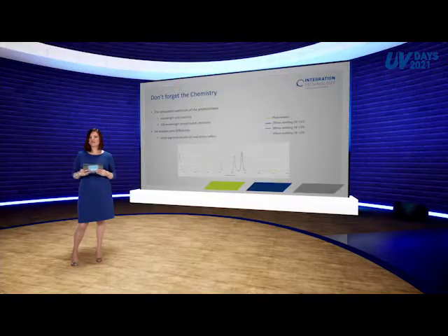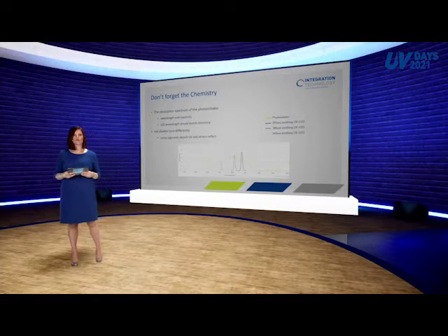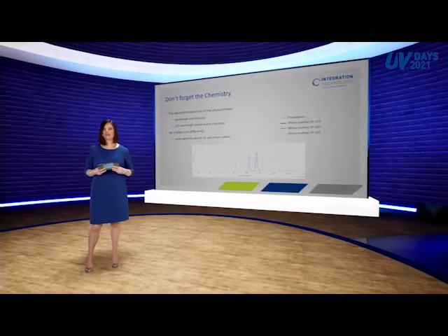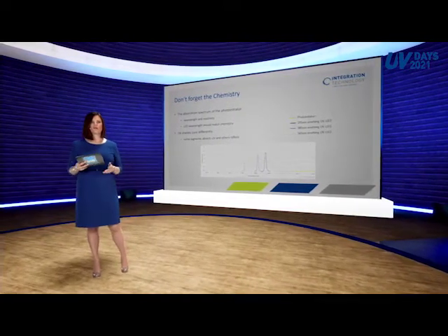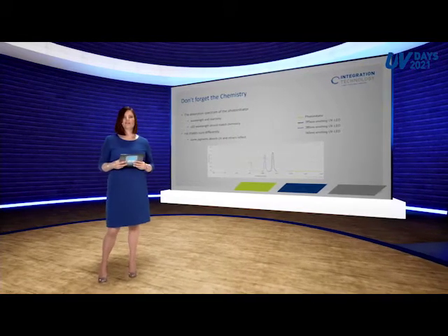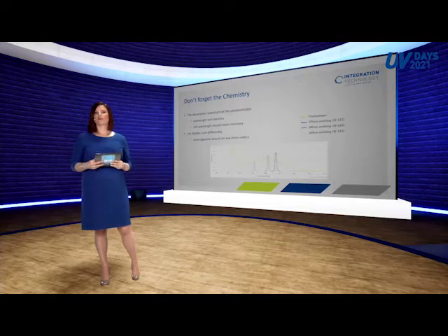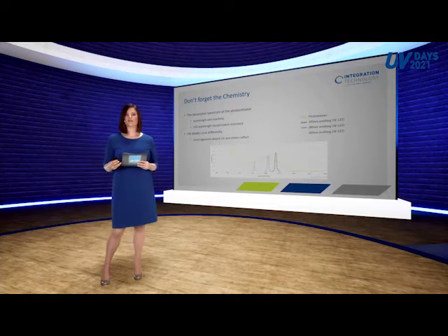Also, consider different colors, for example. If you're in digital printing, then CMYK, they cure differently. Pigments absorb or reflect light differently. So this should always be tested, not just test one color tone. All colors should be tested also.